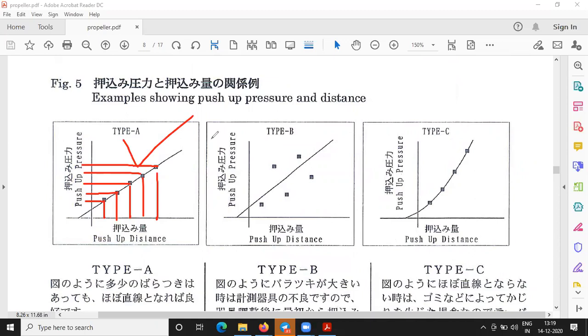So what did we do in the dry method? In the dry method, whatever we used for the pushing up, we are only knowing whether the tool is fitted properly or not, whether the surface of the tail shaft and the propeller boss is free of dust, free of dirt, anything like that, or an improper tool or irregularity in the machinery. One thing we saw was human errors, one thing we saw was the cleanliness, one thing we saw was the apparatus errors.